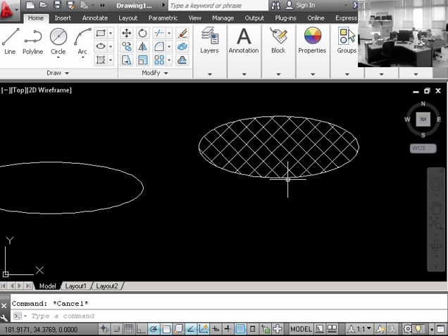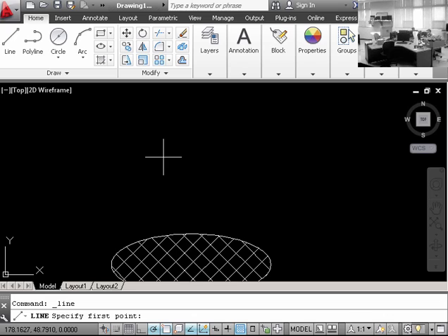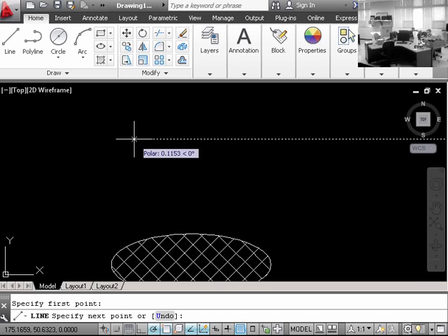I thought I either could remember or wrote down the sequence for the angle. Yep. Sure, absolutely. So when you need to draw a line to length and angle, you give it a start point, right? Okay. Then what's the first thing you type? At symbol. It's the at symbol. At symbol's first, then the length. So let's say we want to make this thing 15 units long, and then what? Well, less than, and then the angle you want it to be. So let's say 37.5. And then you hit enter, and there it goes.